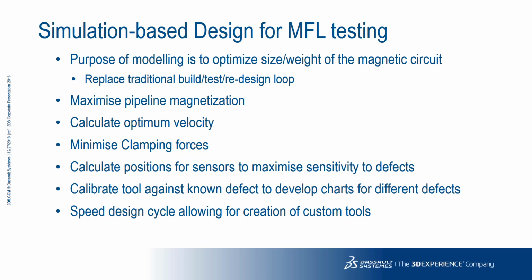The requirements that the tools saturate the pipe and provide maximum fluid bypass are inherently conflicting. Saturating the pipe requires a large area of steel inside the body of the tool to provide a return path for the magnetic flux. On the other hand, achieving maximum gas bypass requires a large bore in the center of the tool. Magnetic clamping forces are directly proportional to the flux magnitude in the gap. These clamping forces should be minimized so as not to adversely affect the smooth progress through the pipeline.